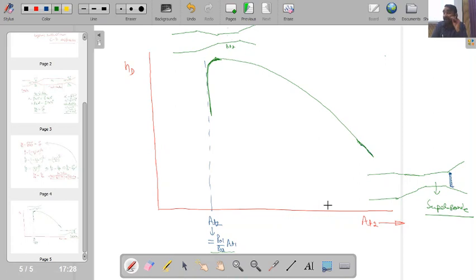Okay, and ultimately it was observed experimentally that for moving that shock wave during the initial transient phase of the wind tunnel, in order to move that normal shock wave out of the complete diffuser, we have to keep this area A2 higher than the area which we are getting from this equation.